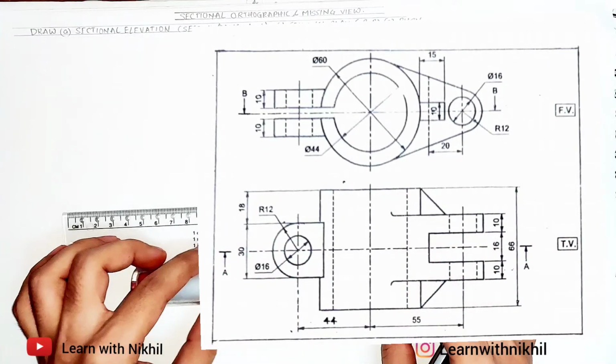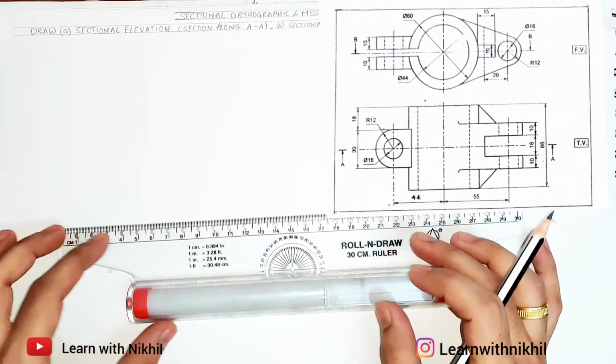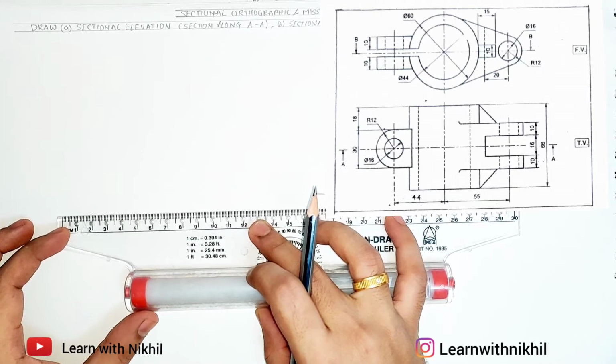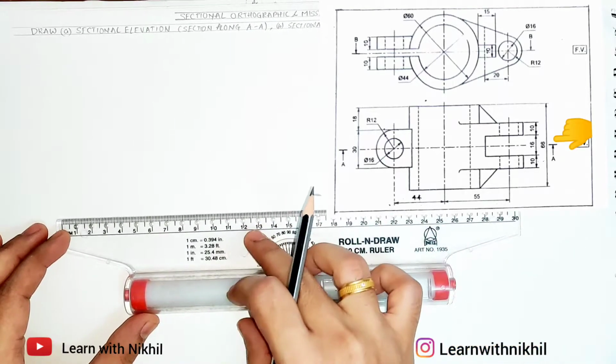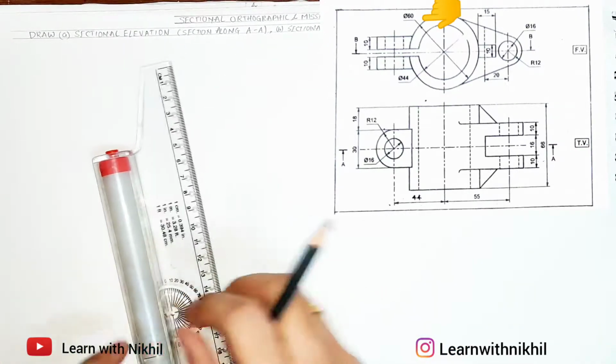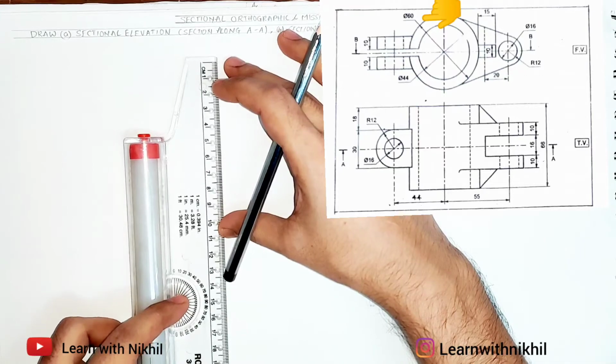So first we'll calculate the total width required to draw the front view. That will be the radius of the semicircle, that is 12, plus 44, plus 55, plus the radius of the outer semicircle, that will be 12. So total will be 123 millimeters. Now the total height required to draw the front view will be 66 millimeters and the total depth will be 60 millimeters. That will be the diameter of the outer circle.